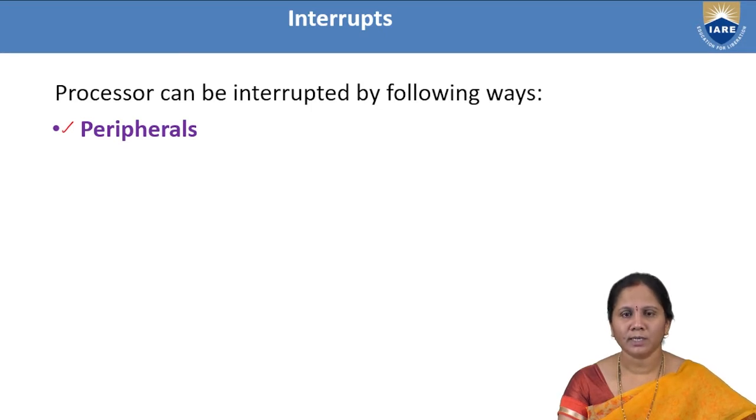If any interrupt is coming through the INTR signal, in order for the 8086 microprocessor to accept that interrupt, the interrupt flag bit should compulsorily be set. In another case, if any interrupt is coming through the NMI pin, that is the non-maskable interrupt pin, that interrupt will be accepted even though the interrupt flag bit is not set.